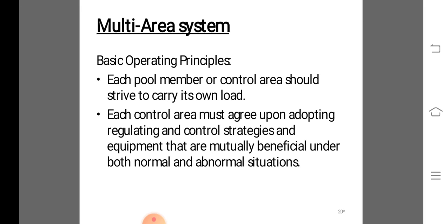In the steady state, consider the two area system depicted. The two secondary frequency controllers, AGC1 and AGC2, will adjust the power reference value of the generators participating in the AGC. In an N area system, there are N controllers, AGC1 to AGCN, one for each area. A common way to implement this is a proportional integral (PI) controller.